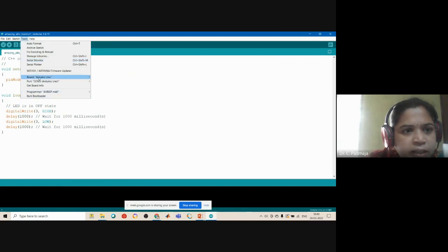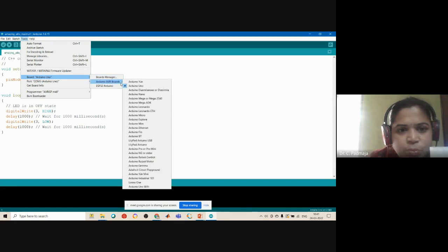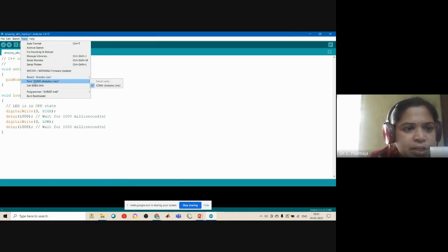And the second thing, I have to select which COM port my USB is connected to for this Arduino. Here it is already showing that it is connected to COM3. So these are the two things I have to do first. First, I have to select the corresponding board. I have the Arduino Nano also; I'll show you later. In the board manager, I have to select the corresponding Arduino I'm using for my prototype. The next one is the port, which I have to select as COM3.